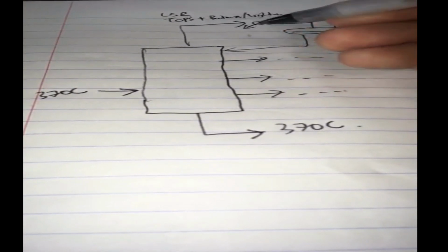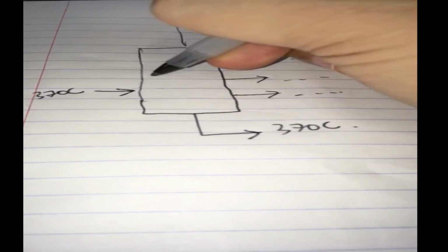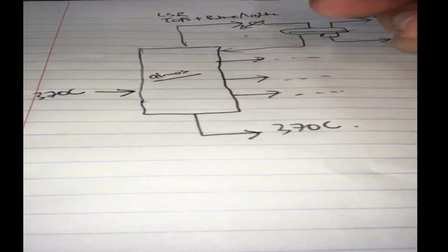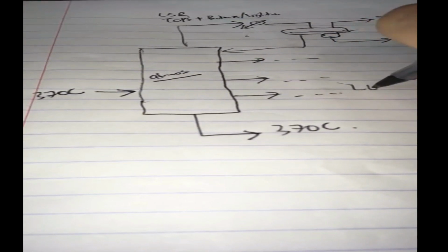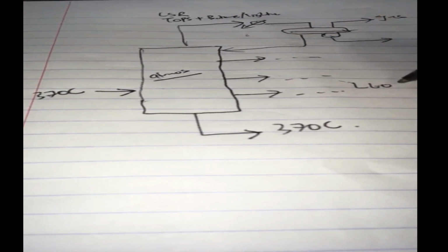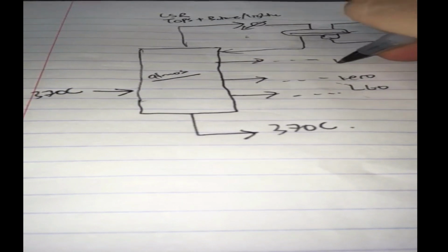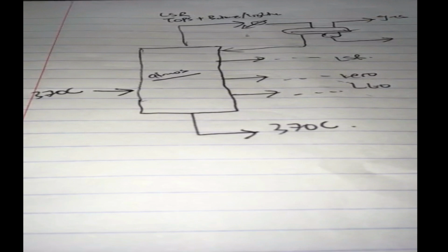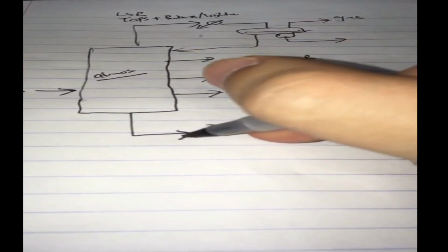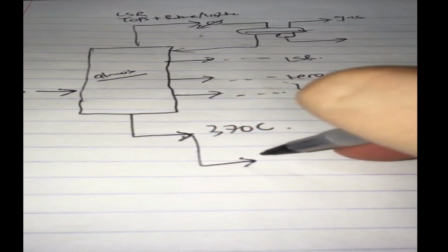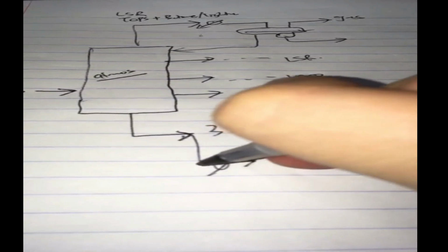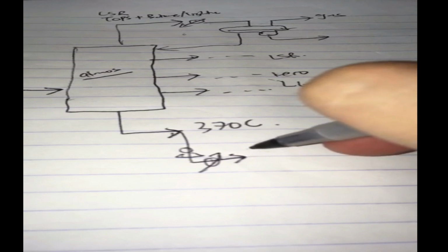So instead of drawing heavy gas oil from our atmospheric tower, we can draw maybe light gas oil plus kerosene plus light straight run gasoline. So this will need to separate even more. And if we want to have our safety barrier, we have a heater and pump again to ensure it is at 370.